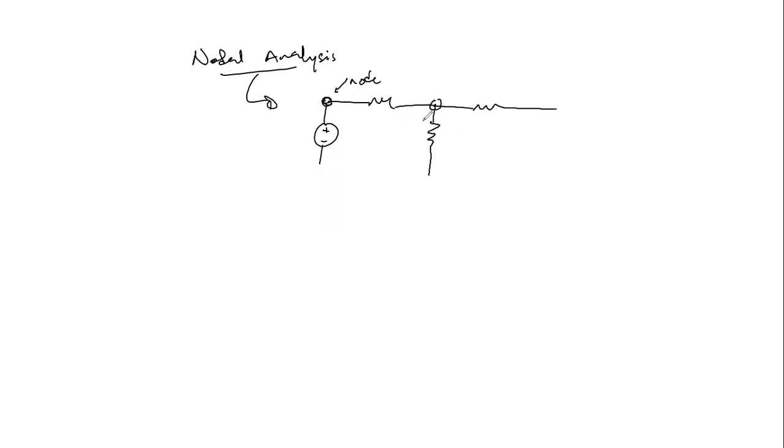And then you see we have about 3 elements. And also in our previous lecture, we made mention of a type of node, which is the essential node. This is the point joining 3 or more elements together. Now, one important point to note here is that the essential node in the circuit helps in identifying a proper choice for the reference node.